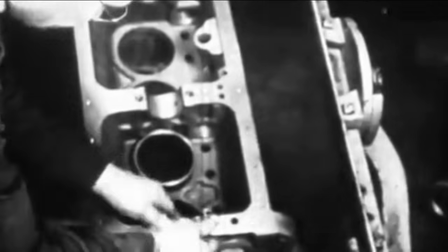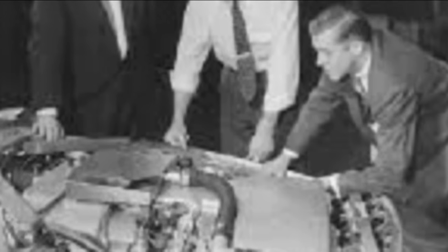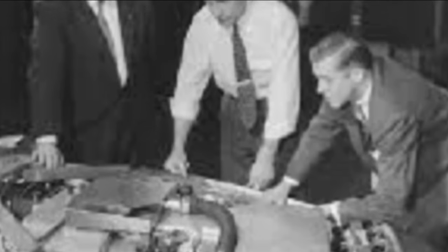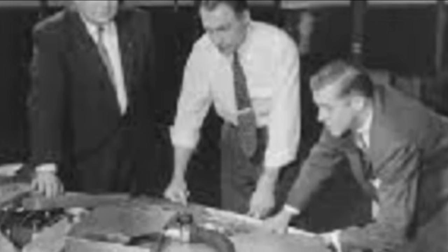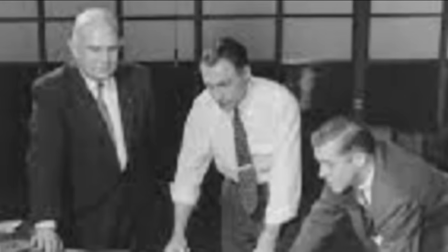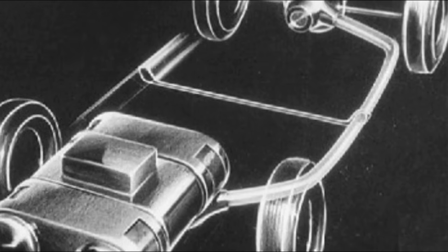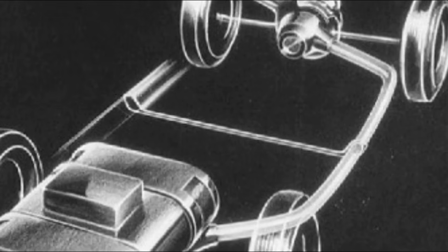Due to the absence of a crankshaft, connecting rods, shaft bearings, flywheel, cylinder head, valves, rocker arms, and camshaft, the crankless engine had fewer parts and fewer friction pairs than conventional piston engines. This should have increased its mechanical efficiency and wear resistance. Furthermore, due to its complete balance and the absence of harmful vibration, this engine could be installed on a simpler frame. Since the gas generator and turbine were independent units, their installation on a tractor was very convenient.